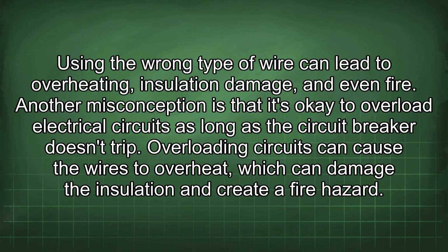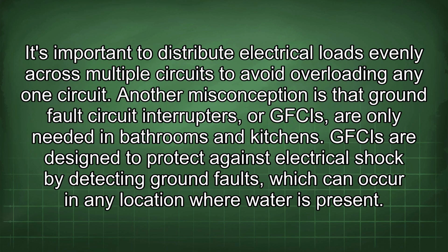Another misconception is that it's okay to overload electrical circuits as long as the circuit breaker doesn't trip. Overloading circuits can cause the wires to overheat, which can damage the insulation and create a fire hazard. It's important to distribute electrical loads evenly across multiple circuits to avoid overloading any one circuit.